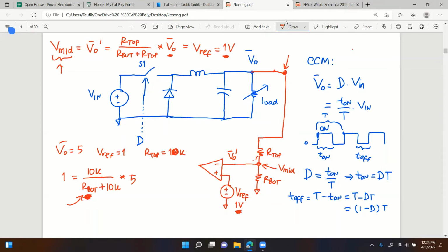You get the sampled output voltage by setting up the proper resistor values, you have the reference voltage, and the output goes through more circuitry, the PWM circuitry, a box we'll also discuss next week. Its output gives you the proper pulsing with the required duty cycle.